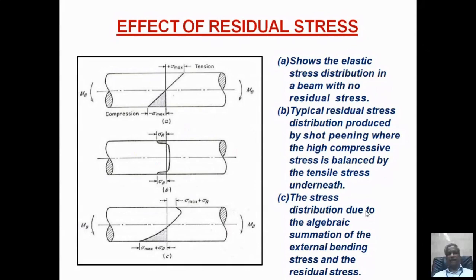And this is the rotating wing fatigue test machine. Again, it's a tabletop machine. So it will hold small specimens, 10 mm diameter. The dimensions are fixed. Only maximum diameter it can hold is 10 or 12 mm diameter. You cannot test more than that.